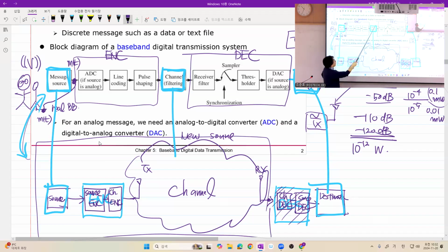Got it? And then your radio wave is received by the receive antenna, filtered by a pre-select filter, and amplified by a low noise amplifier, and possibly an image rejection filter and heterodyne receiver structure. And then you may have two real baseband signals, in-phase and quadrature. So even though it appears that there is only one sampler, you may have two samplers in reality.